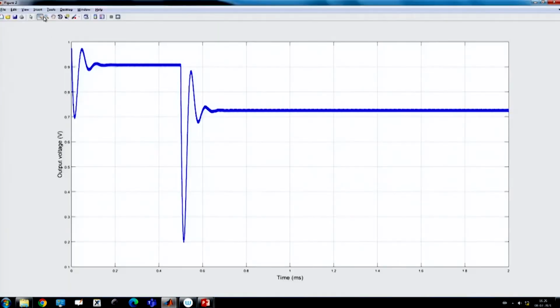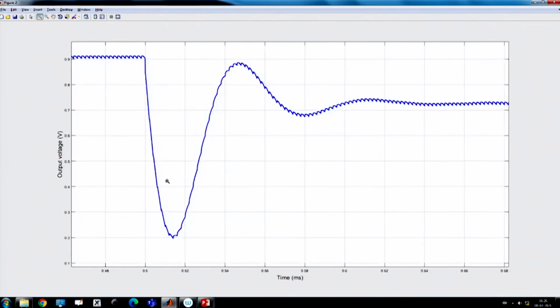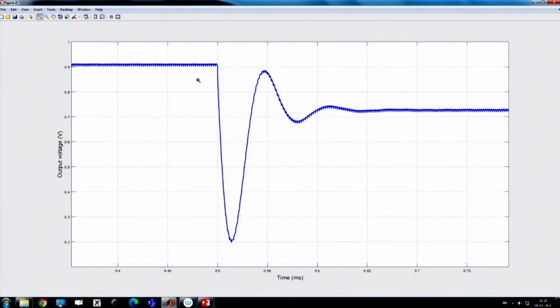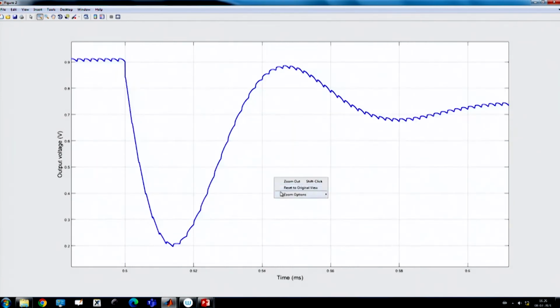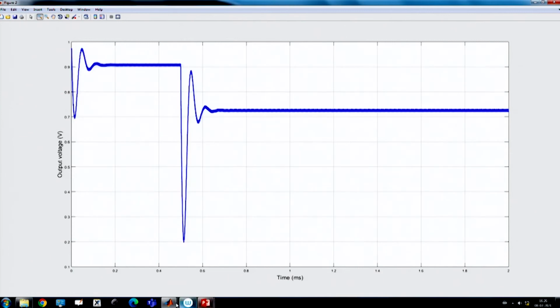You see, this is our output voltage, because it is open loop, and we have just discussed that in open loop the steady state point will get shifted because there is a DC drop. The DC drop can be visualized by considering a series resistance, the output resistance of the source. So, a DC-DC converter can be treated as a source, which in open loop behaves as a finite output impedance DC value. It also has a transient effect that we saw in the previous simulation, and it is also clear here.